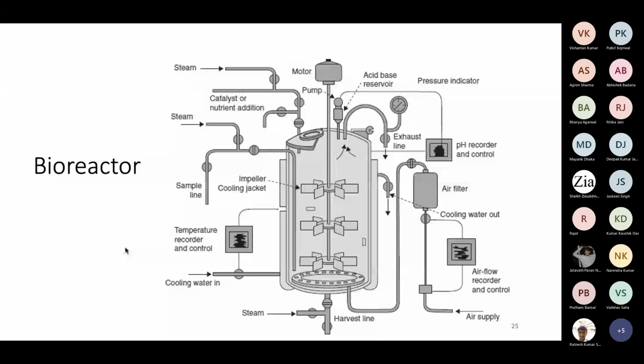But in all reactors, they will have certain limit for temperature variation and rotational speed, because these materials are temperature sensitive and also they're shear sensitive. Means if you create excessive amount of shear, the bacterial cell will actually get disrupted, and due to cell disruption, entire process will fail. So you have certain upper limit to get mixing mediated by the stirrer movement.